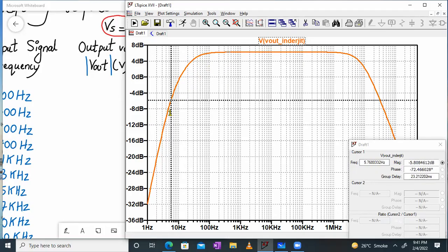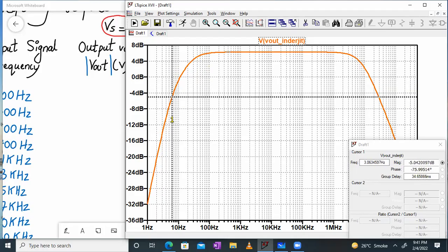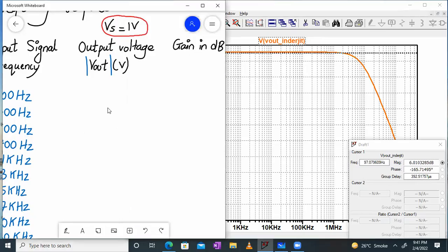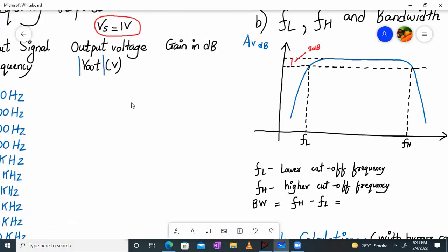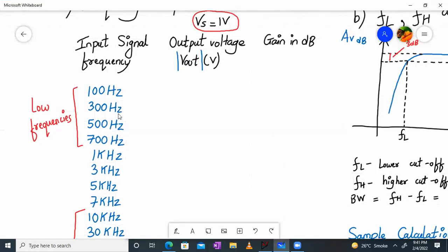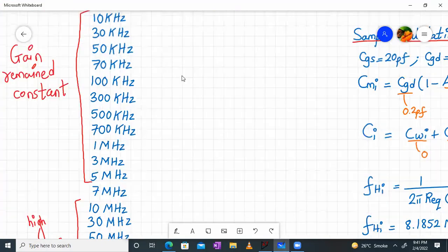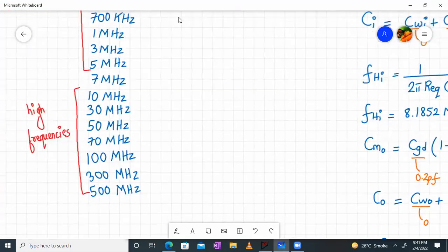I mean, I can take it at extremely low frequency. In this case, it's starting from 1 to 10, and then it goes to 100 also, right? So to collect this reading, I have to do some modifications over here. The low frequencies are too low, so I have to start with 1 hertz onwards. No need to go till 5 megahertz.